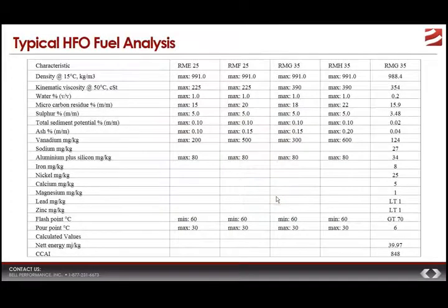Now, these are typical properties of heavy marine fuels that are in use today. You can see that all of these have specific properties that are deemed necessary enough to be adhered to that they need to be measured. So some of the ones that we can see, you can see density and viscosity. These density and kinematic viscosity, these affect the energy value of fuel, and specifically the viscosity affects how the fuel gets atomized into the combustion chamber.